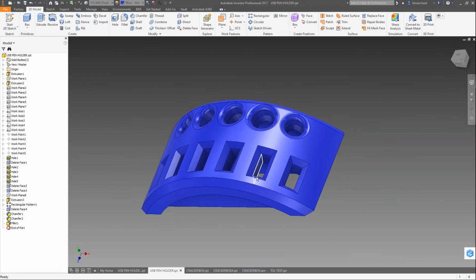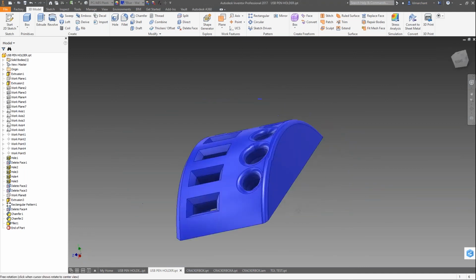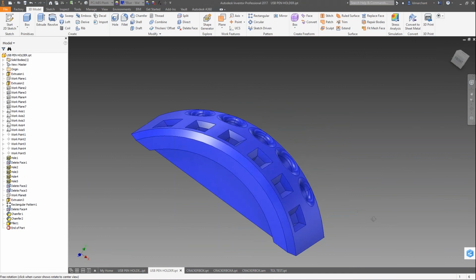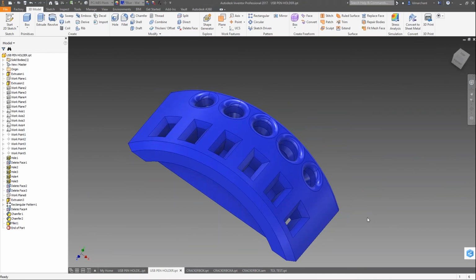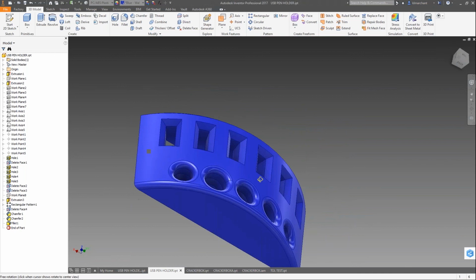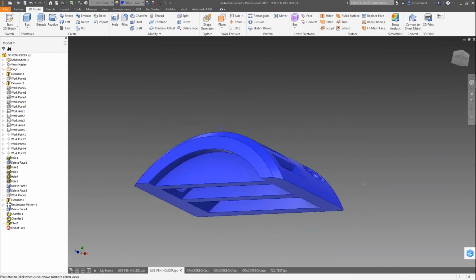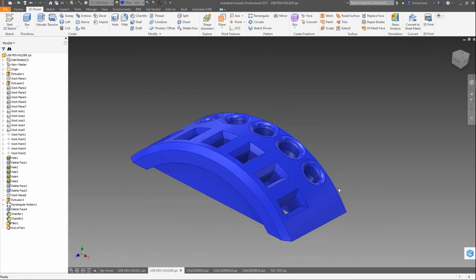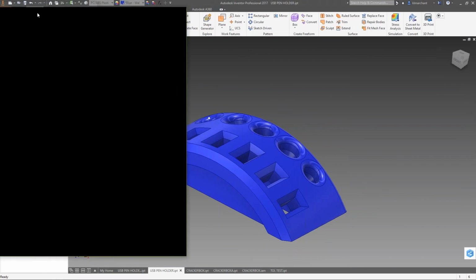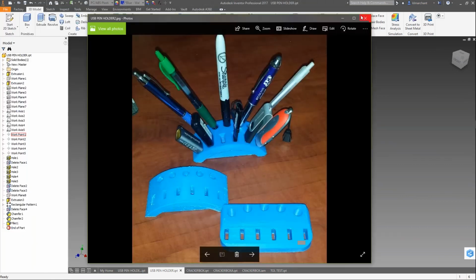The other advantage to this is I did all this from design 1 to design 2, which included redesigning my USB shapes because they didn't fit the first time around. My tolerances were too tight. I think I had 1 or 2 that fit all the holes, but I had a couple others that were a little bit bigger and didn't fit. So in the wonderful world of standardization, I just made everything a little bit bigger. And with that in mind, I printed that out, and it works.